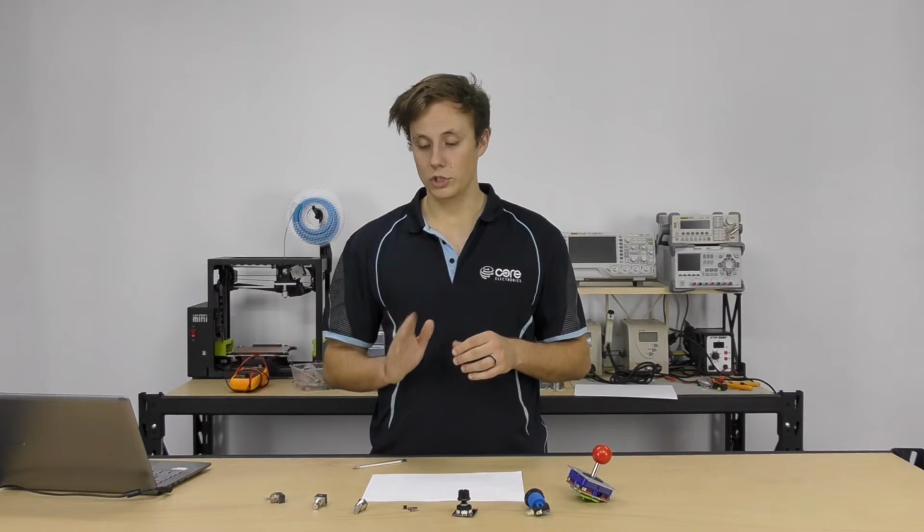Momentary switches are the opposite. If you imagine the clicky point on your pen again, except when you push it down, the pen nib comes out, and then when you let it go, straight away it goes back up. It doesn't hold its position. That's a momentary switch. It's really good for selecting an input or changing something momentarily, like a press and hold kind of switch that turns off when you release it, or a pulse that can be read by a microcontroller to develop a latching function. That's momentary versus latching.